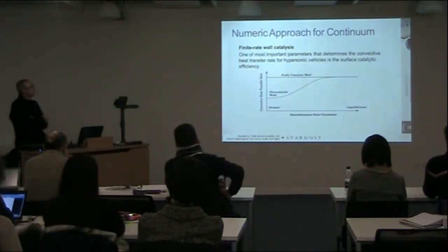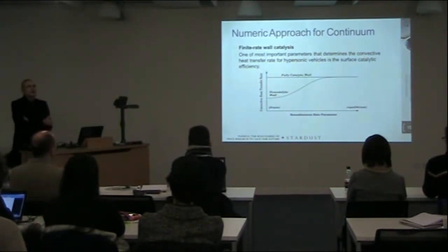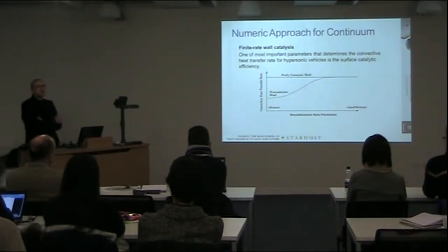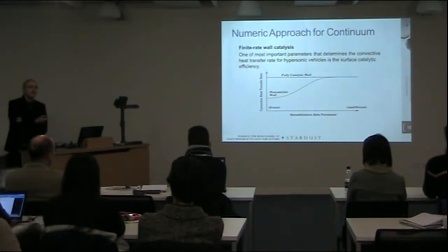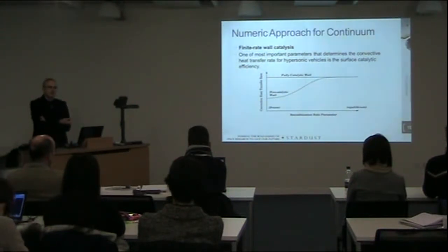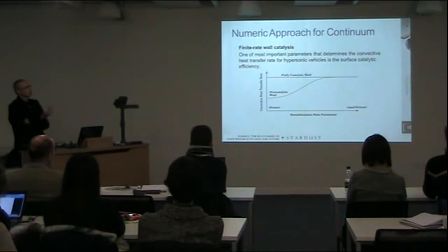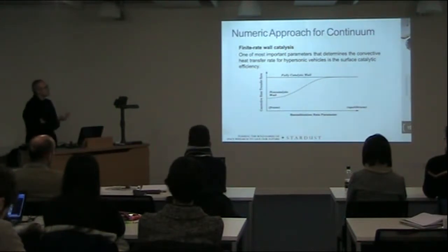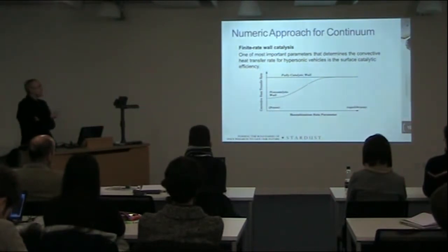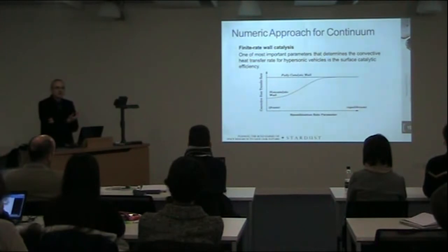And in order to give boundary conditions at the wall, another thing which is not easy to model is the catalytic efficiency of the wall. So how the wall and the material of the wall is affecting the chemical reactions in the flow. And again, in this case, simplified solutions can be obtained in a cheaper way if you consider a fully catalytic or totally non-catalytic wall, and that gives you again some bounds.